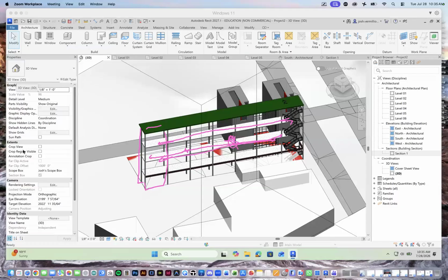So again, let's just zoom out for a moment. This is a steel frame, and steel performs under certain norms. It's pretty strong stuff until it gets up to a certain temperature, and after that it starts to fail structurally. When we try to create routes to get out, and we try to add fireproofing to steel, we're not necessarily trying to save the building. We're trying to keep the building standing up long enough for everybody to get out safely.